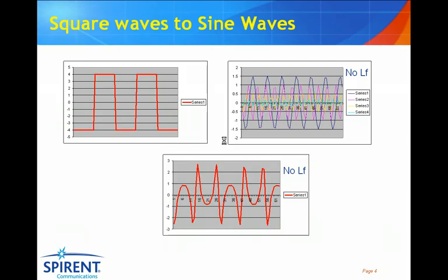It's by taking out the high frequency components within the picture that we can apply additional compression. However, there is a point: if you take out too many high frequencies, the picture will become noticeably softer. Typically, this is easily spotted if you see some text on the screen and you see a form of ringing around the edges of the text. This means that most probably the picture has been overcompressed.